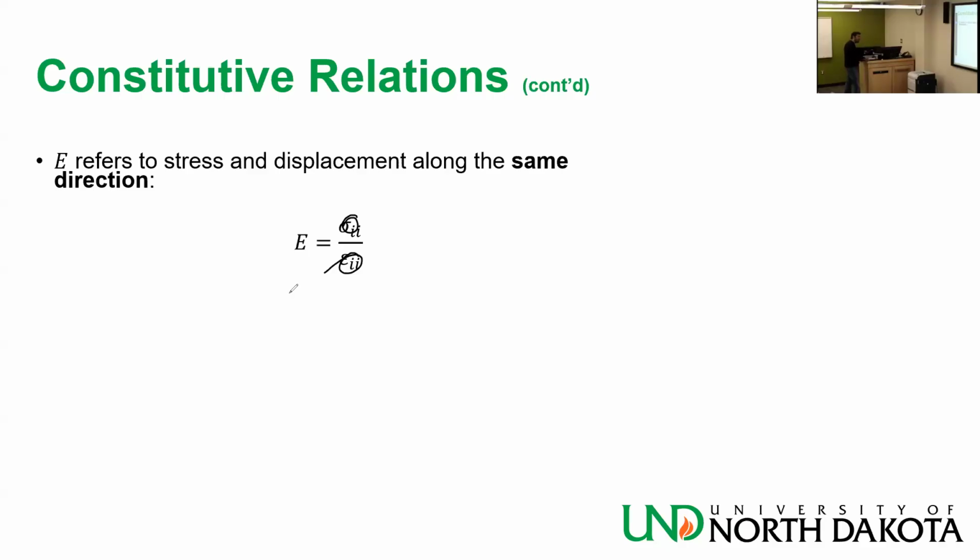So you put the load on it, you measure how much it shortens, you divide by the original height, and you divide the stress of the load that you put above it by that shortening divided by the initial height, and you have the Young's modulus, basically, in units of stress or dimensions of stress.